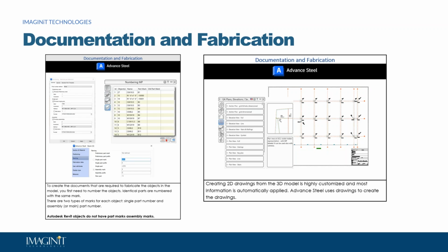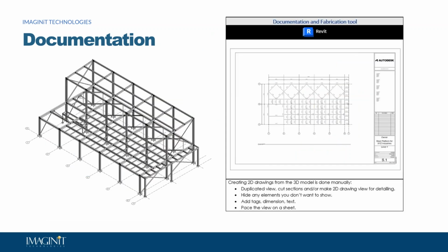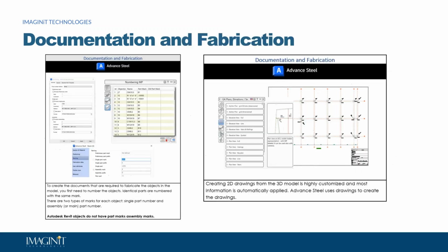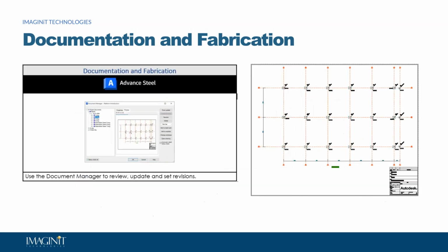Okay. Whereas up here in Revit, I make a change and the model is going to make a change in my plan instantly. Hence the word Revit, revision instantly. Oh well, anyway, yeah, cool. This is a little bit different in here. I have to pick a button to update. Still fast. Okay, so also through fabrication drawings is where I can make things like DXF files and NC files to go out to my CNC machine if I'm doing fabrication. Depends if you're doing that or not.